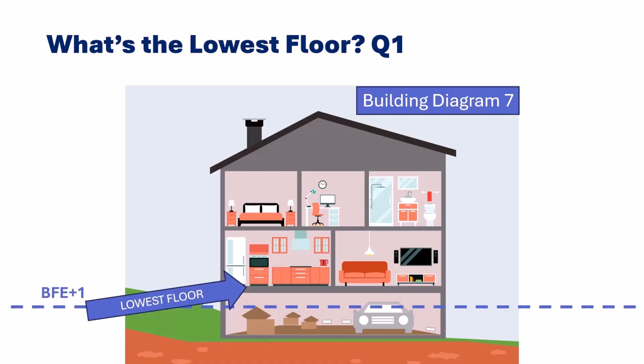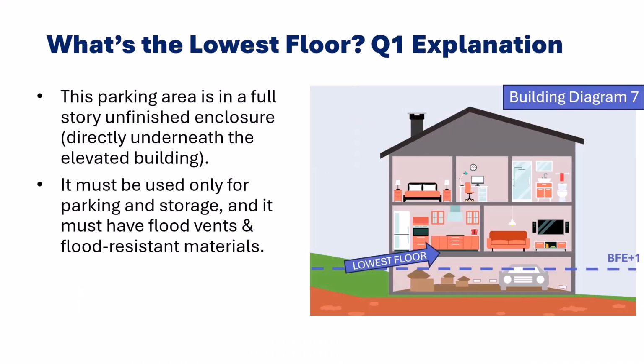It'll be this one. The parking area shown on the bottom floor is in a full-story unfinished enclosure directly beneath an elevated building. If it's used only for parking, storage, and building access, is unfinished, and has proper flood vents and uses flood-resistant materials, it remains the bottom floor, but is not the lowest floor for floodplain management purposes.